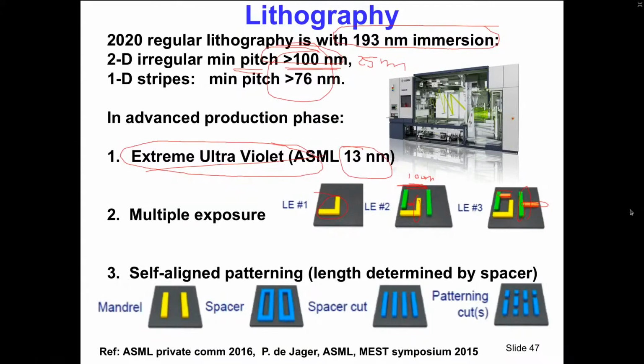The obvious problem is, of course, the overlay. How accurate is the yellow aligned to the green and to the orange over here? Because that is then the limiting factor. And really, if you go to the manufacturers and you ask them, please, what is your overlay? Then you will get a very nice big smile, but nothing else.